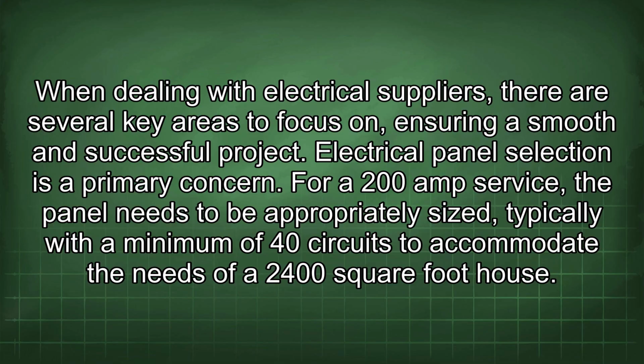Electrical panel selection is a primary concern. For a 200 amp service, the panel needs to be appropriately sized, typically with a minimum of 40 circuits to accommodate the needs of a 2,400 square foot house.